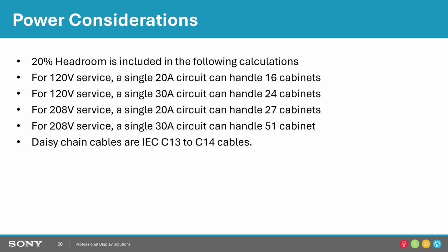A 20 amp circuit handles 16 cabinets. This is all configured with 20% overhead figured into that. The daisy chains between cabinets, which Sony does provide, are IEC 13 to 14 cables that daisy chain between cabinets for the power.